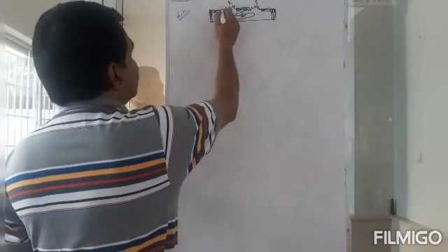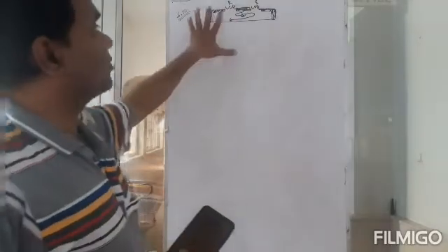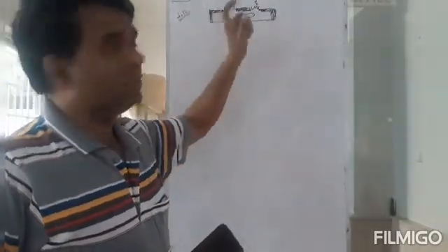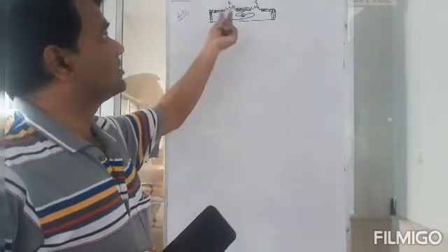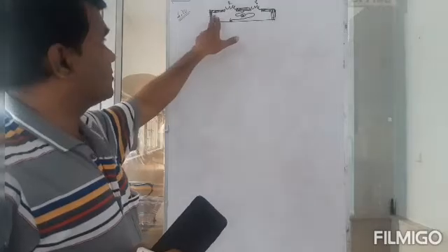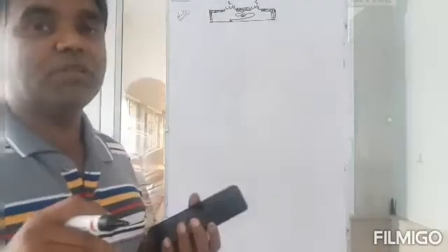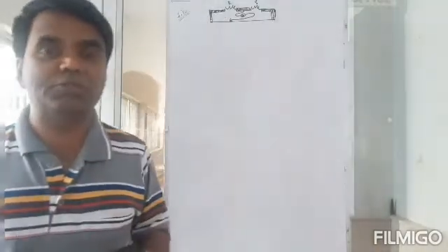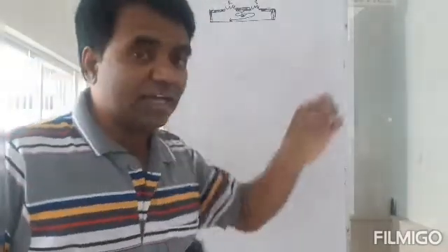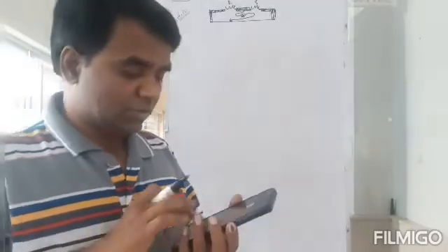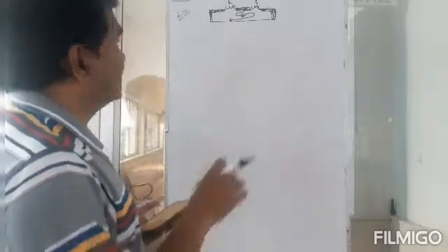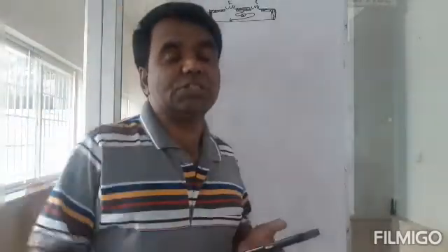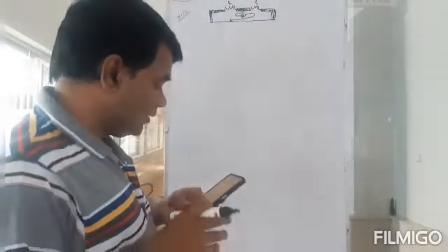The thick connection is given here because you don't want this to have any resistance at all, or you want the connections to have negligible resistance. You want all the resistances to be concentrated here, R and S, and this must be of negligible resistance. So that is why, when you have a Wheatstone bridge or meter bridge, the connections between the resistors would be done using flat and thick copper strips, so that the connectors' resistances will be negligible. So that's the reason.